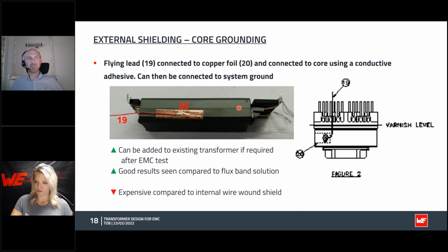So if it's bigger, then the whole conducted emissions frequency spectrum will have a higher noise, whereas the leakage inductance will only show up at a few frequencies, which can be easily filtered, as I mentioned, or snubbered, where it doesn't cause such an impact on the EMC.